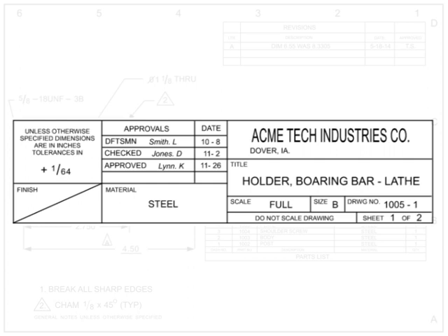The remaining areas of the block can be tailored for other information such as material, heat treatment, finishes, weight, general specs and standards, next higher assembly information, or superseding information. Other boilerplate information such as copyright information, export control information, design activity, and manufacturing information may also be included in or next to the title block.